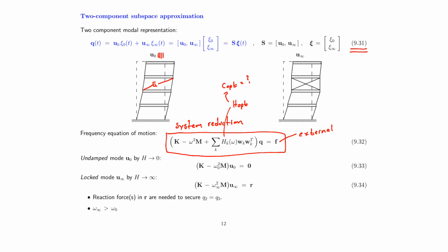Now, modal analysis tells us that the full displacement vector is given by the undamped vibration shape times the modal coordinate. However, the presence of the damper, as indicated here by this red connection, of course has an influence on this vibration shape. So only including this undamped vibration shape would not provide us with a very accurate model. It turns out that we need a correction. We need a second vibration mode. And it's not the vibration mode for the second mode or the third mode. It's also a vibration shape for the first vibration mode. It just looks a little bit different.